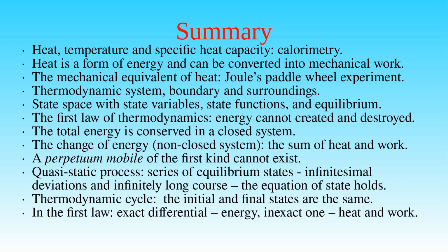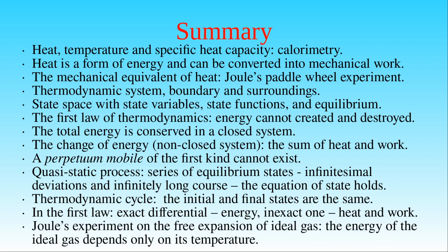We could apply the first law of thermodynamics with the explicit formula of the pressure-volume work to calculate the technical work of a steam engine, and introduce the enthalpy of a thermodynamic system, which is a state function. We finished the presentation with another application of the first law of thermodynamics, namely Joule's experiment studying the free expansion of an ideal gas. We saw that no heat exchange was measured between the gas and its environment in this experiment. Based on both the law of conservation of energy and the ideal gas law, we could establish that the internal energy of the ideal gas only depends on its absolute temperature.